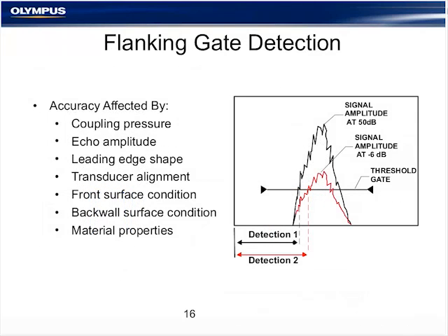Now, the detection algorithm, I mentioned before, Olympus has a very specific way of measuring repeatably and accurately the backwall reflection from a dual transducer. And there are actually two factors involved when we look at the comparison between this automatic thickness gauge detection algorithm and something more standard on a flaw detector.